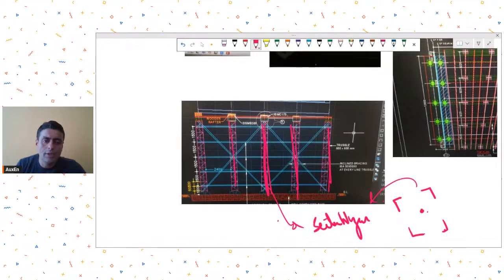On top of it, you could make your primary beams, and on top of the primary beams the secondary system. Of course, in STAAD you will not be able to do it at a two-tier level, so at the same level you could model your secondary system. On top of that secondary system, you could apply loads. Generally, load application can be done as one-way slabs, because shutterings are usually composed of steel plates, and they are usually supported across their short span.